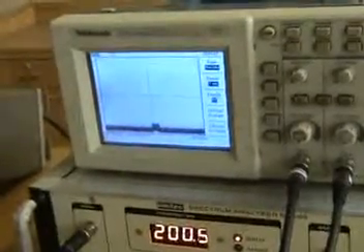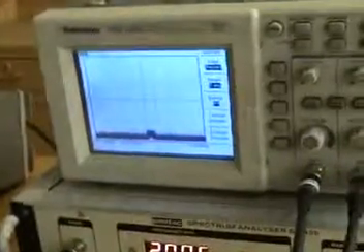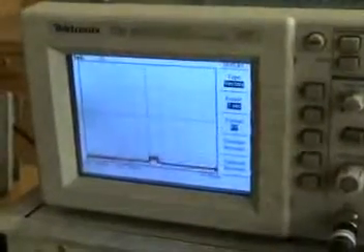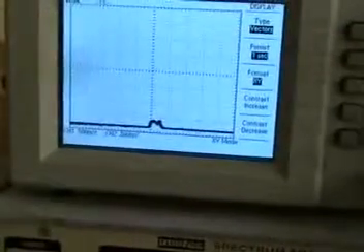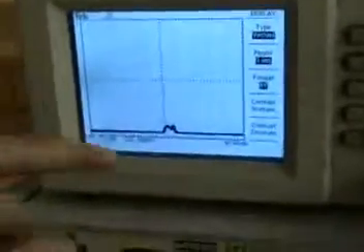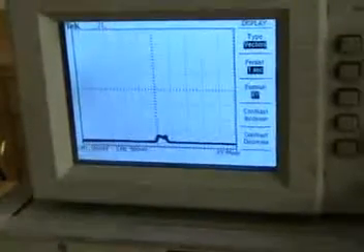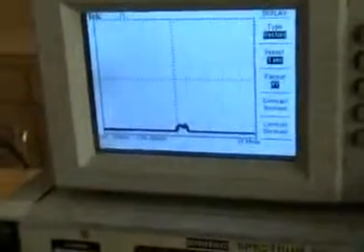97 dBm. So minus 97 dBm, and the signal is still higher. You can see by adding the video filter, you can see the signal, and the signal level is around 7 dB here, and the calibrated level is around minus 97 dBm.